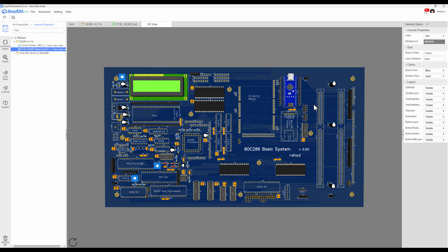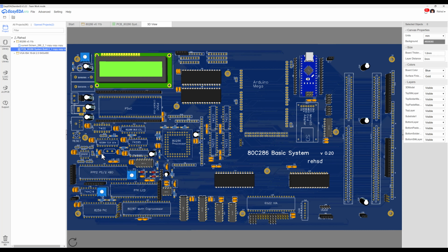First things first, I've removed the need for the external clock and power card that I've been using. Typically in the upper left, I've had this PCB up here that's providing clock signals so that I can single step or run through a slower or faster clock, and also giving some power distribution capabilities. To support that, I've put an onboard crystal. I have a crystal along with a couple of capacitors that I can now feed into my clock generator. And that means I do not need a separate board to do that.